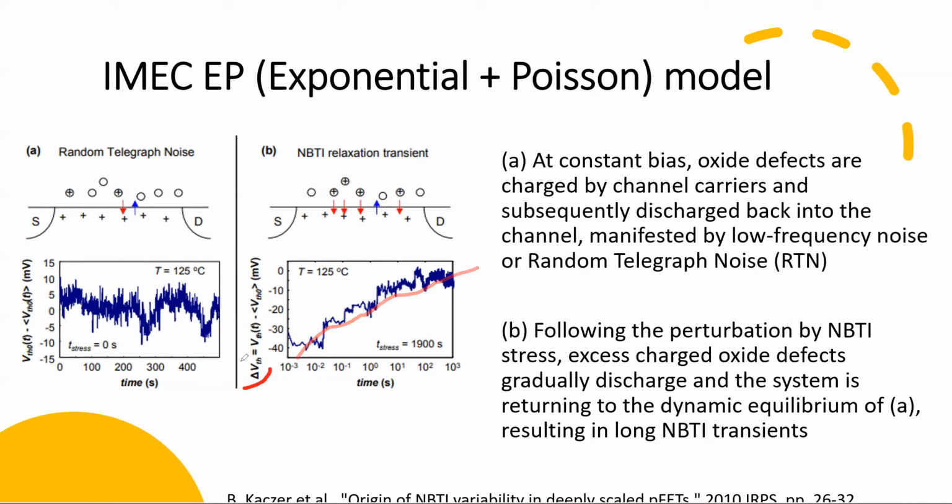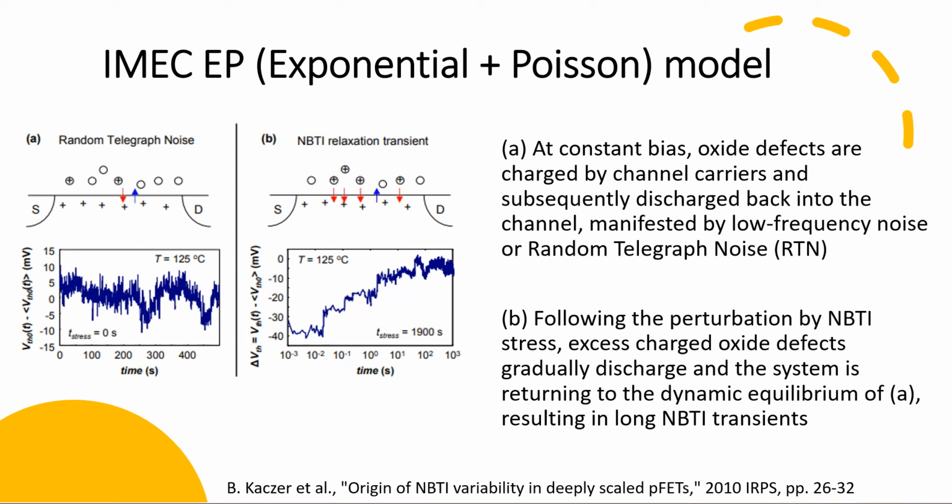The drift is reflected in your threshold voltage drift. You drift up at high temperature. High temperature means that you are accelerating the process to make it happen, so you can have a signal. Otherwise, you take forever to get a signal. So all these, they propose a different mathematical form, and that makes sense to them, and it turns out they did a much better job.